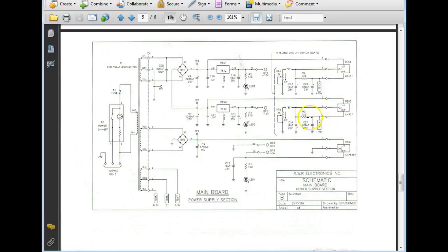Here's the voltage divider, and here's your pot wired as a rheostat. As soon as you take the wiper of the pot and connect it to one side, it acts like a rheostat. So what's the difference between a rheostat and a pot? What do we use pots for? Voltage. And rheostats for current. So if we vary the current here, we change the drop there. So these are pots wired as rheostats, and you're going to see that a lot. You can actually make a pot serve two functions.